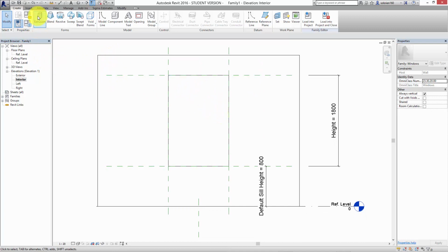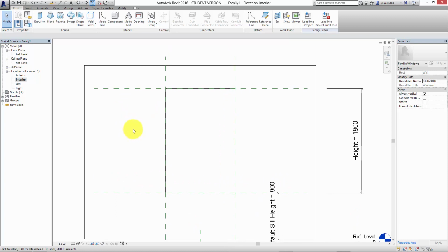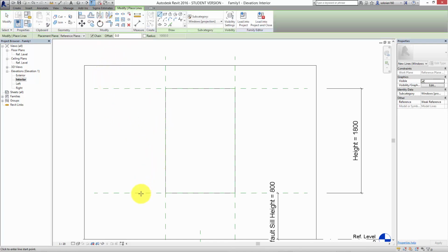We just make an extrusion effectively. So let's say, I'm just trying to think, let's make something that's along the lines of a window with some glazing bars in it. And I'm going to make a very simple one, so I'm not going to worry too much about the modeling of the glazing bars. I'm just going to assume they're all kind of square because I don't want to complicate it too much at the moment. So let's set up, first of all, some model lines that we can use as references. So I'm going to draw a model line at the bottom here.